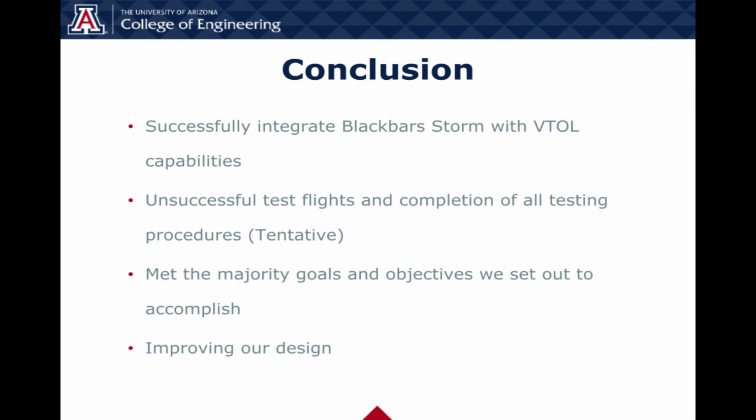Finally, we would like to make some final remarks about the project. We would want to look more into improving the aerodynamics of the craft, as many of the booms create a lot of increased drag and weight. If we were able to somehow get these booms to fold after transitioning in the air, or maybe place them within the wings of the aircraft, this may drastically reduce the drag of the aircraft.